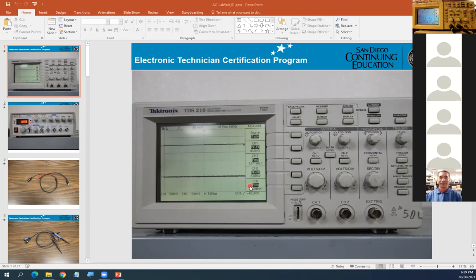So again, the question is when do we need channel 2? You want to measure the phase angle difference. Exactly, that is the one. Why do they want to measure the phase angle? That means they compare the phase of the input on channel 1 to the phase of the input on channel 2. Then you must connect both channels.